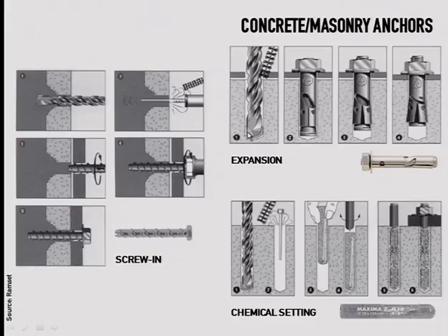After the pilot hole is drilled, you place this cage that once the bolt is in, it tends to expand so that it's fixed and you can't take it out. And what happens with the chemical setting is that you drill the pilot hole, then you place the product in, and then there is friction while you are tightening the bolt, and this friction heats up the chemical product that tends to react and expands, and then again you create just a single material.